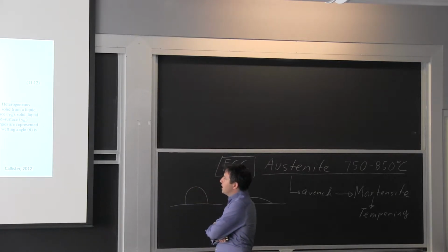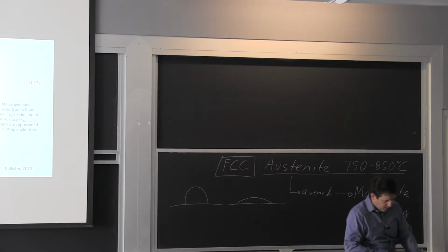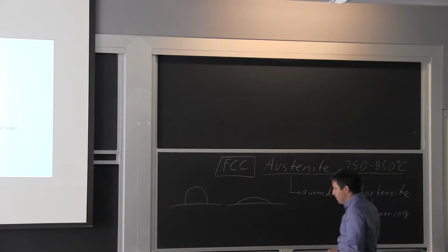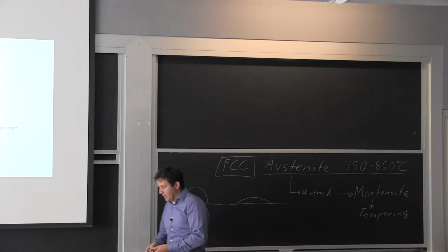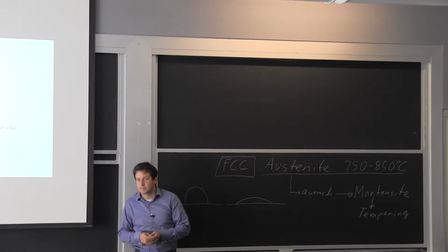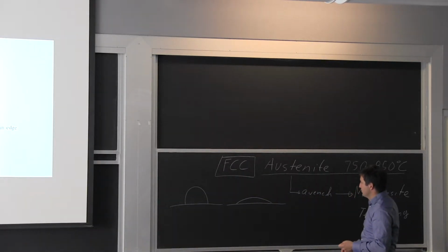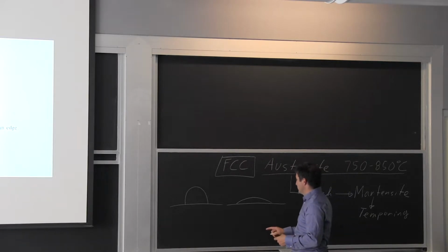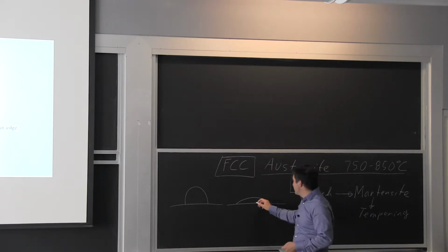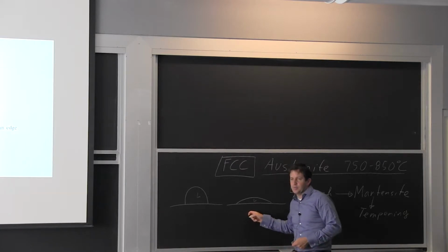The reason why it matters is we've discussed for solidification, you're always going to have this critical volume that you need to make the phase transformation. We were essentially dealing with a liquid, and I was saying, well, if I want a little piece of solid, yes? So why does the wetting angle change so much with temperature? Is that because the surface energy or the surface tension is changing? Surface tension is reducing, yeah, when the solid temperature is going up. So say this is the liquid, and what I'm changing really is the temperature of the substrate.